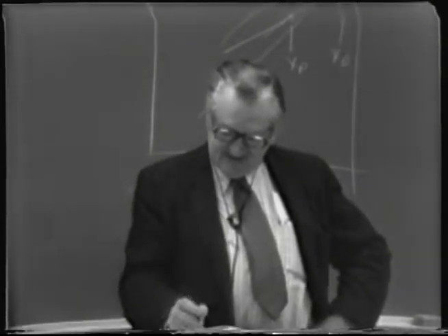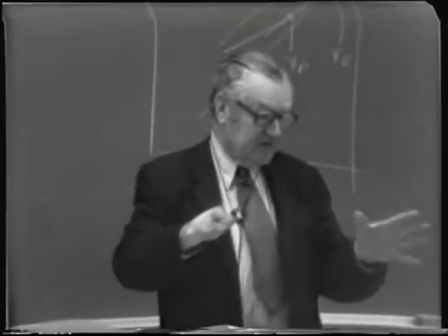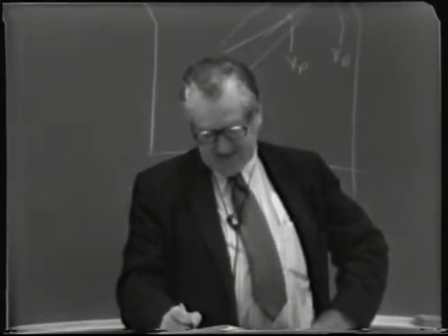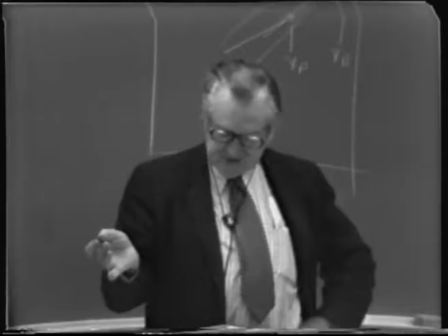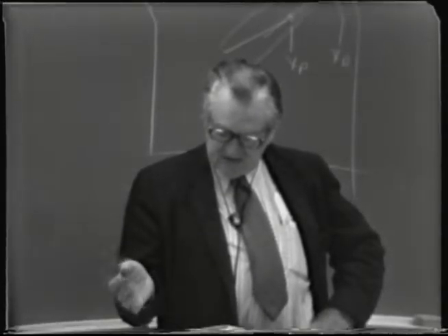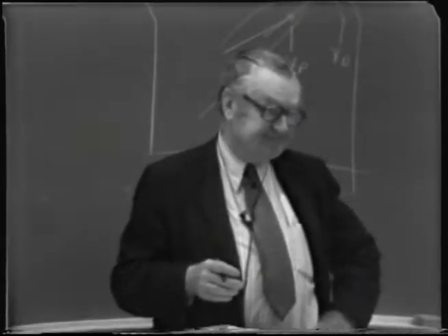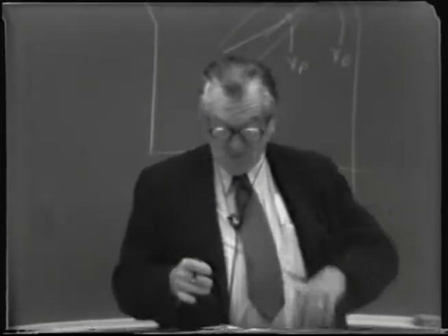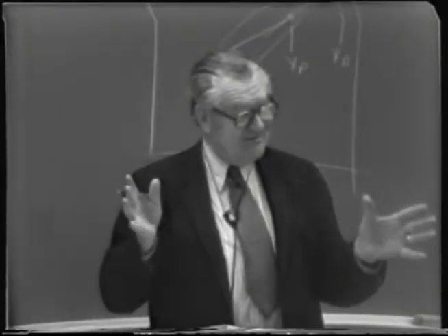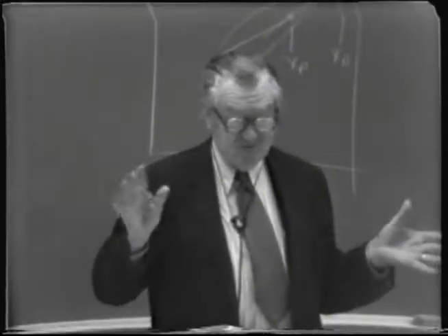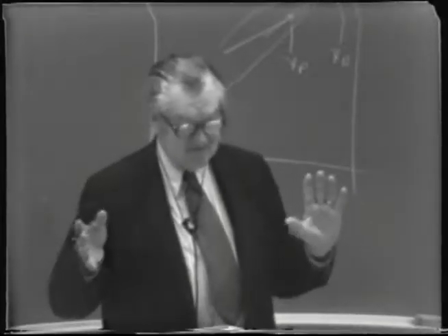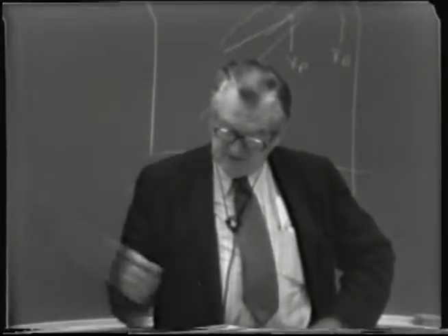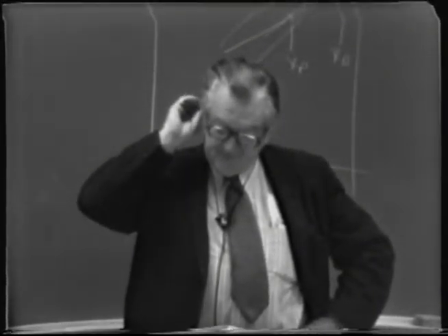Now that is the only meaningful ratio that we got here, but in parentheses I've calculated that this would be equivalent to an overhead product external reflux ratio of about 1.86 to 1. But there's no point under a situation like this where there's any reflux ratio that you can measure 1.86 to 1, because of the side stream method of product removal.